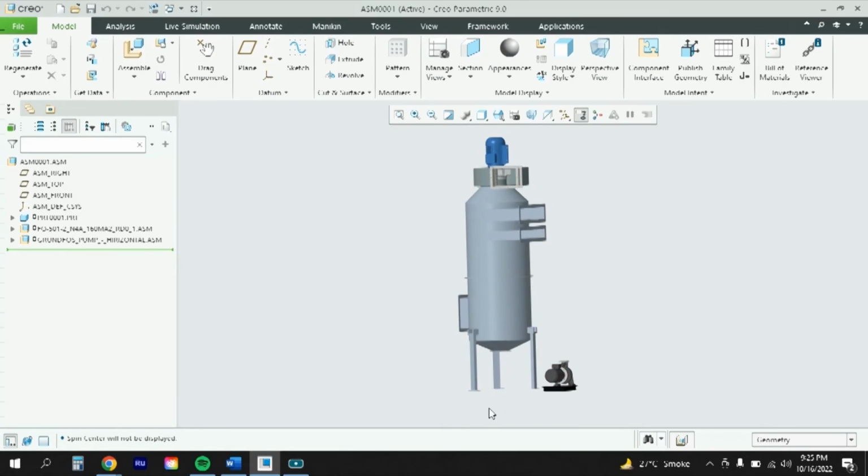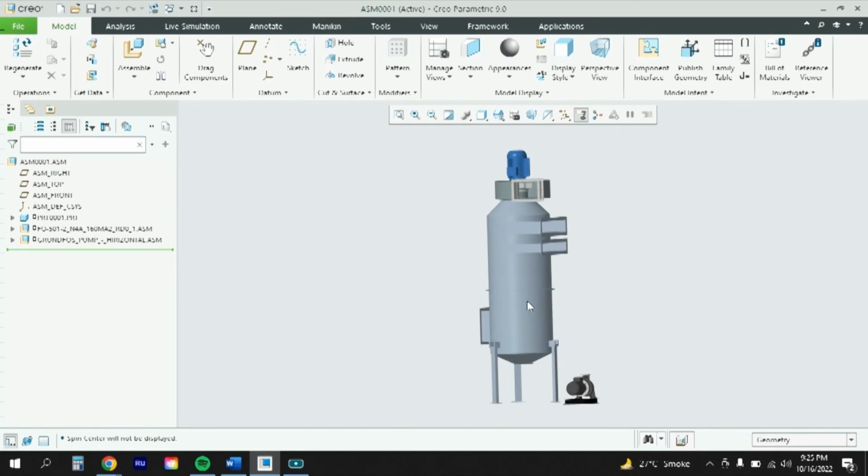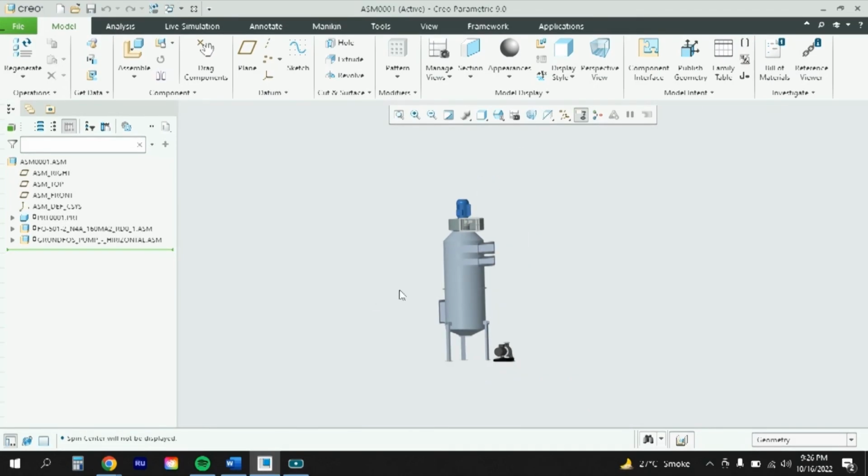You can simply connect this pump through the tank where the water is cleaned, slightly cleaner than the one which is here. So in this way you can save the water as well, and you can use the similar water which you are using for cleaning the air. You can use the same water for recirculation and keep your filters wet. So that's how a wet scrubber works, and I hope you like this video.